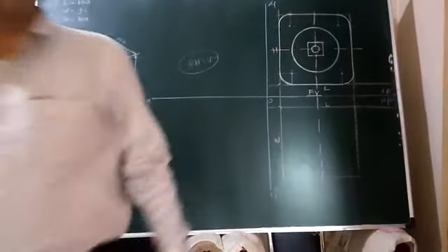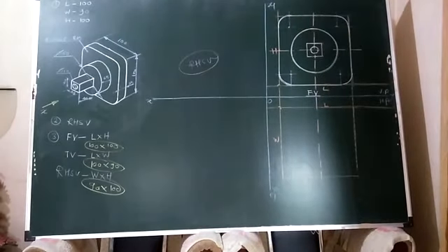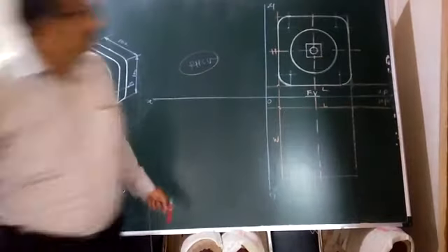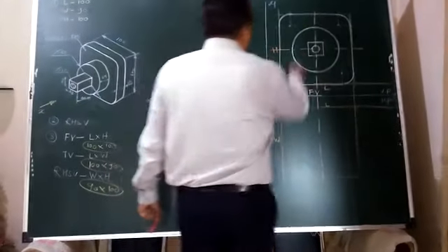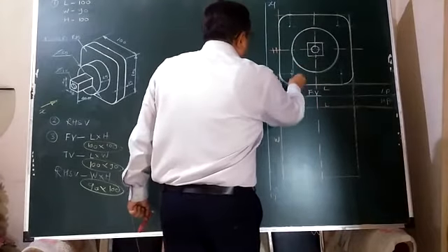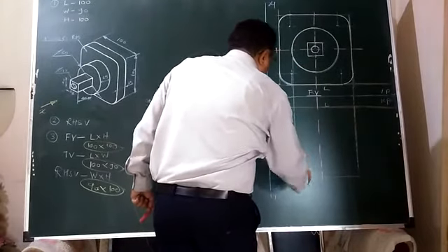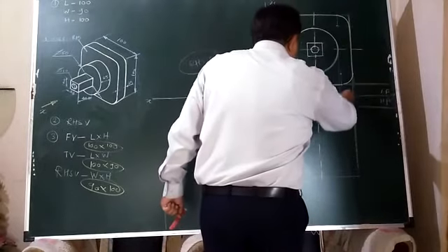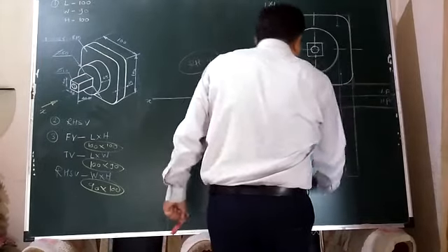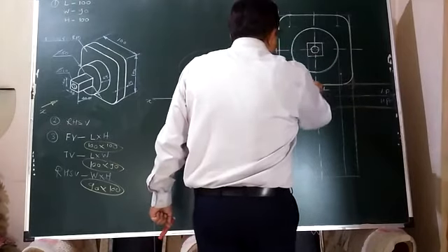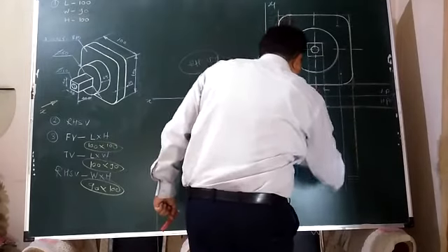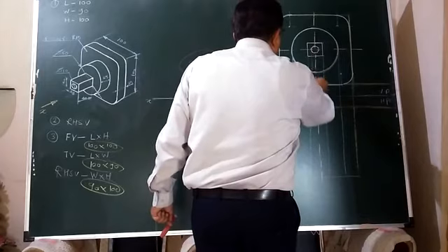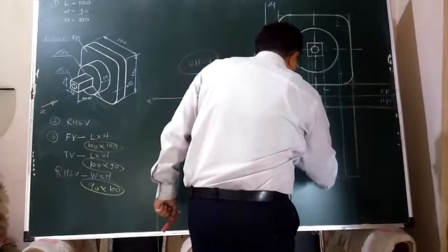Front view is completed. Now we will move towards the construction of the top view. So now, blindly, you have to stretch the projection lines from all the centers, all the elements which are appearing in the front view. Just project it down. Now see here, observe carefully what I am doing. From all the diameters, the center line I have projected earlier. This square also I am going to project here. Similarly, the 10 mm diameter hole, that is the cylindrical hole, that also I will show here.